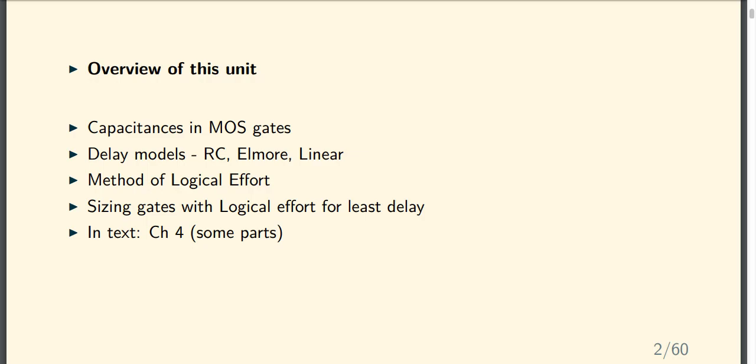Use series parallel combinations, convert it into one capacitance, and the product of those two is what is called the RC delay. That is, if I just multiply R and C, the number that I get is a measure of the delay of the circuit, and that is the simplest way to measure the delay, which is also called the RC delay. That is the first thing that is highlighted under delay models.